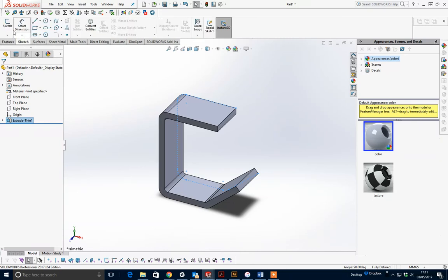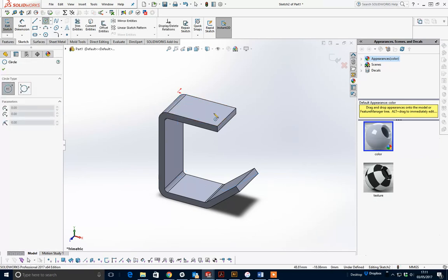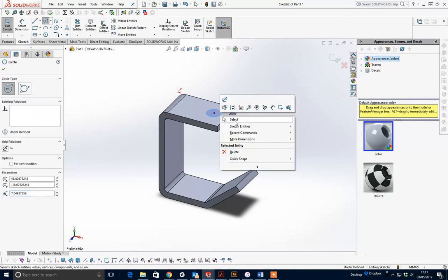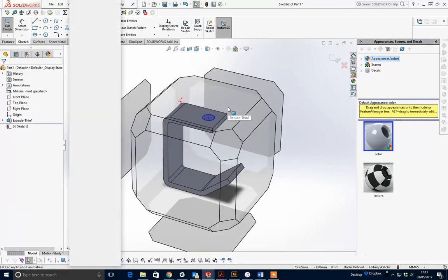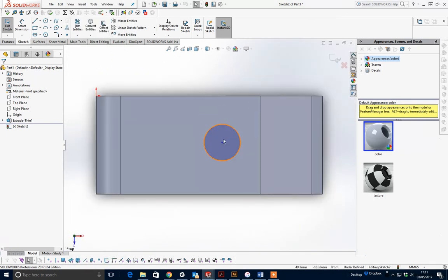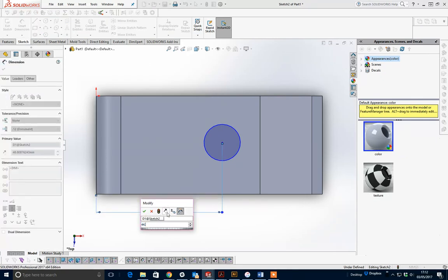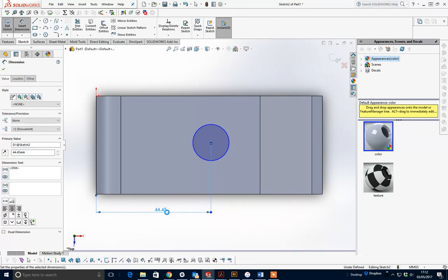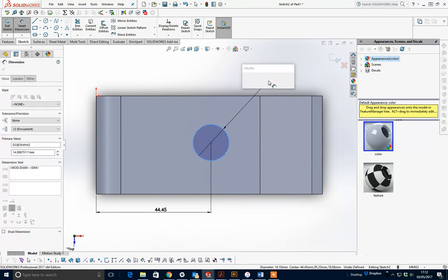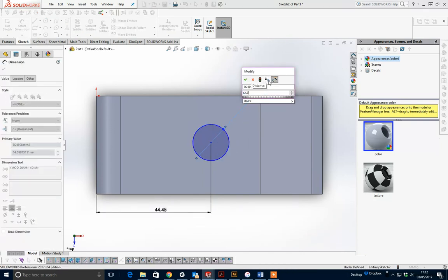So remember, go to sketch, I'm going to pick that top face, and draw a circle. There's the circle. Now I need to actually position that, so I'm just going to press the space bar. Now how far a distance are we looking at there? From that back end to that point there, I put a Smart Dimension in, from there to there is a figure of 44.45. Perfect, see it move. I'm still not defined. While I've got the tool there, I give that a diameter of 12.7.